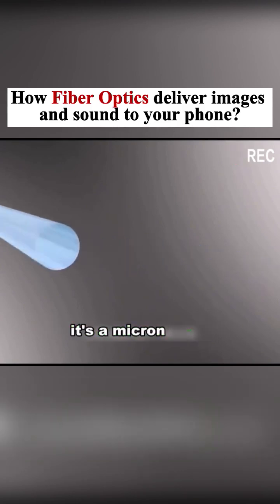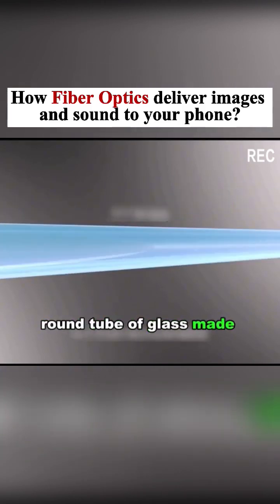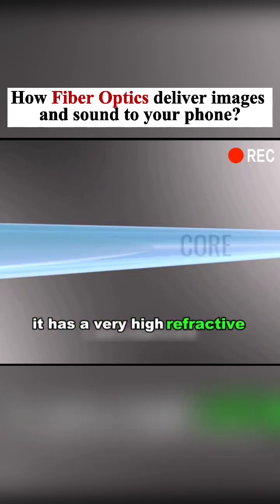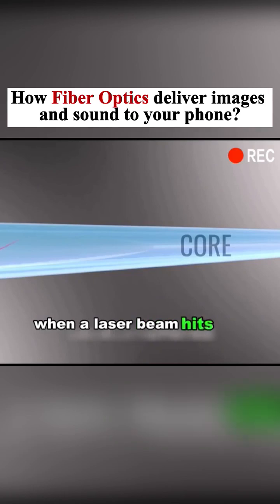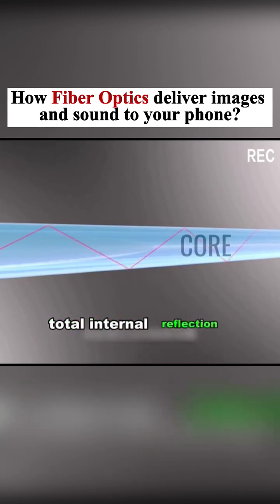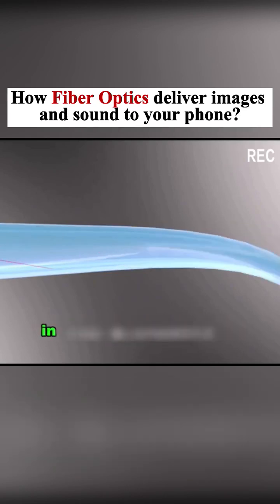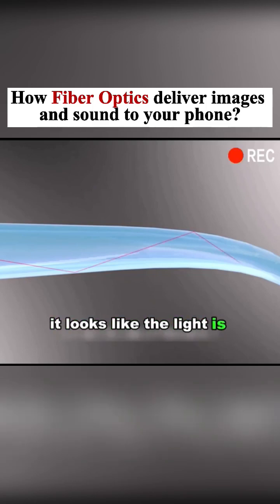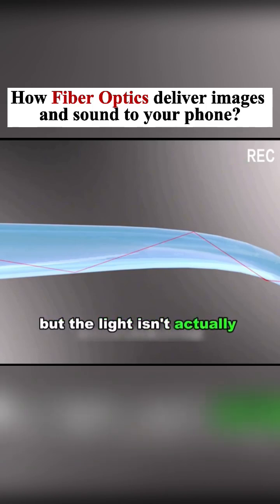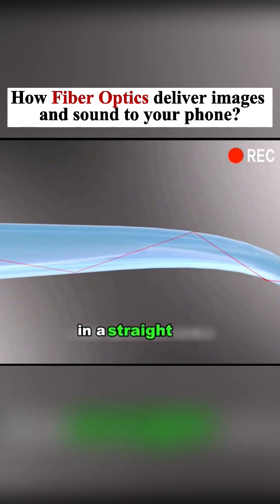It's a micron-sized round tube of glass made from ultra-pure silicon dioxide. It has a very high refractive index. When a laser beam hits the interface at an angle greater than the critical angle, total internal reflection occurs. This means that the light travels all the way to the other end in total internal reflection. From the outside, it looks like the light is bending along the fiber optic cable tube, but the light isn't actually bending, because every time it's reflected, it's moving forward in a straight line.